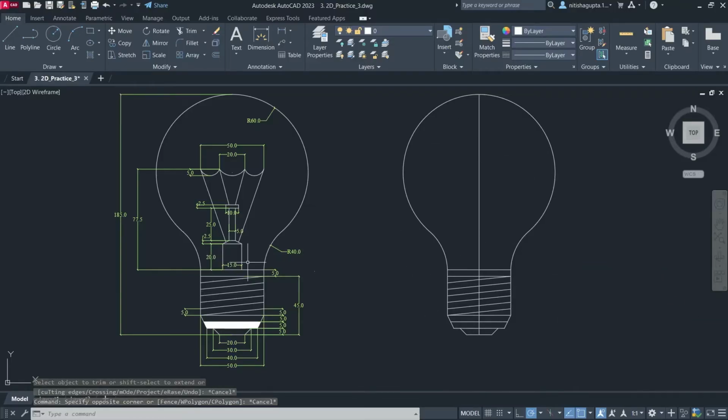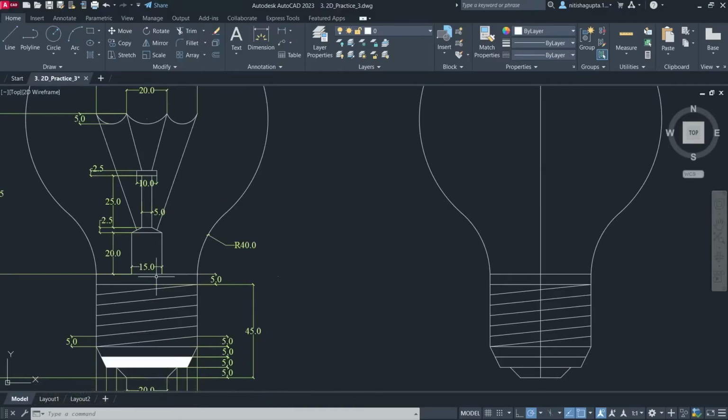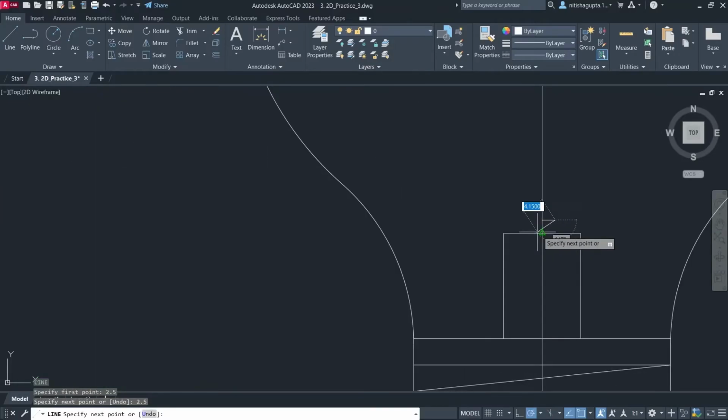Now we have to make inner portions. So let's just do like this. We are having this rectangle of 15 and 20. So let's go to this line command. Half will be 7.5. So enter 7.5. There 20. Now our line will be 15 this side. I'm at the bottom. Make it perpendicular and escape. Now we are having another trapezoid. So just extend to 2.5 height. Towards right it will be 2.5 because our width is 5. And let's just join this and press escape.